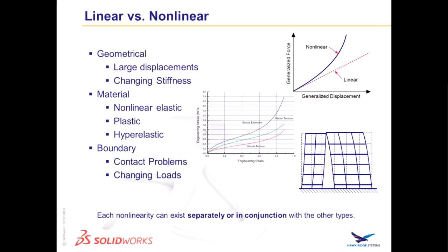So that means we're able to do any problem where we might want to apply a load and then take the load off. For example, if we're trying to do a metal forming analysis or check what the permanently deformed shape of a part is, if it's been yielded. We're also able to do complex contact analysis. For example, gear tooth interactions as they're turning, or clip engagement, or anything where components might be bumping or sliding together where the shape of them or the positions of them are changing as the loads are applied.